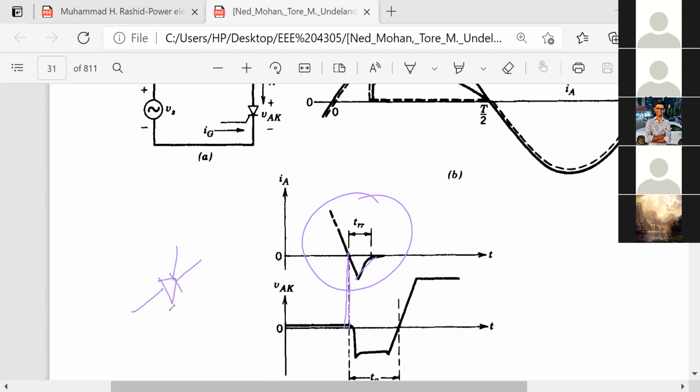If it is on, then what is the voltage it should be? The supply voltage. Yes, sir, in the on state it is short circuit. If it is short circuit, then voltage should be what? Zero. That is why they say that the voltage is zero.